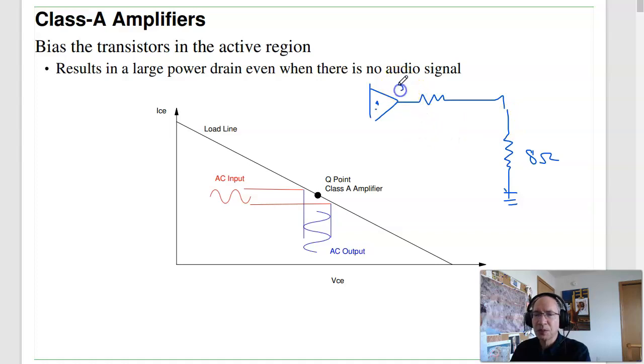So this is going to be at most 5 volts. 5 volts at 50 milliamps is 100 ohms. So this has to be at least 92 ohms, probably like a 100 ohm resistor. So add a 100 ohm resistor in series, and these op amps can drive the speaker. That's going to make it kind of quiet.